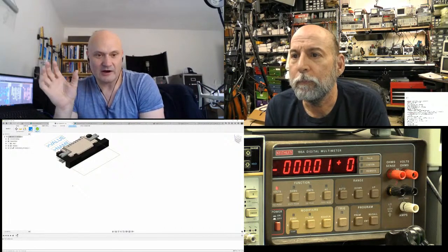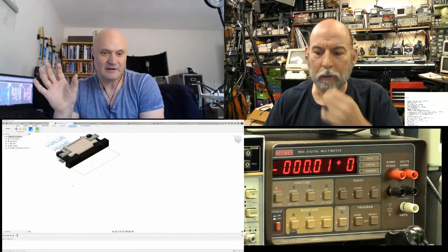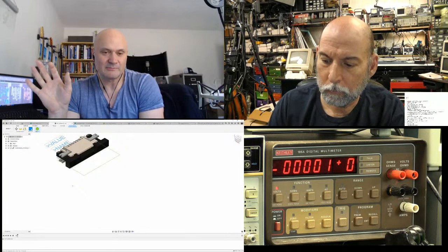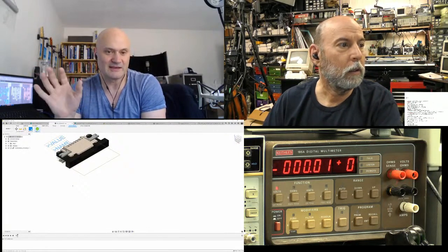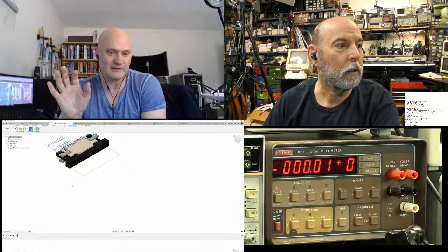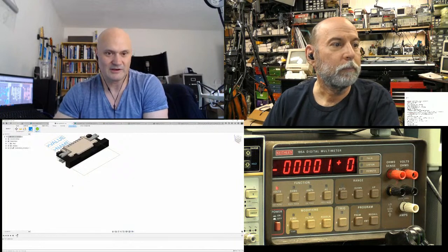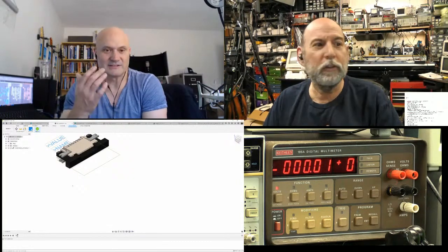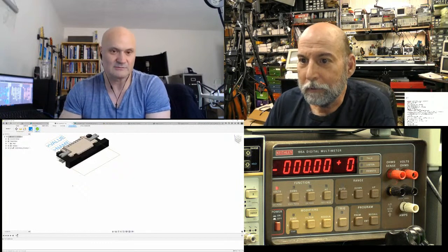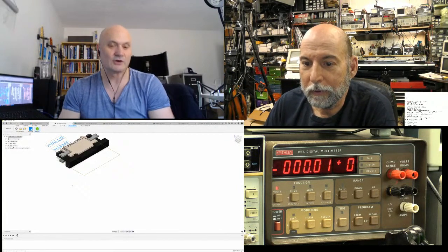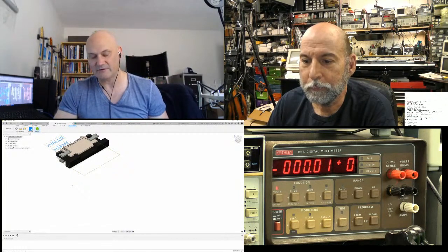I was saying I copied their library, their footprint and symbol and 3D model. I copied the footprint and symbol from the Espressif library to my own and added a 3D model. But then in the board, there was a keep out on an internal copper layer, which was incompatible with my layer stack for this board. And I couldn't delete it, and I couldn't figure out how do I get that out. And then I went into the library. I realized it was in the library, and it could have stopped me going to Gerber. So you've always got to check everything.